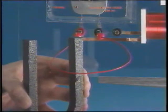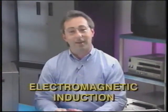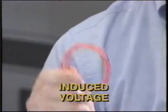So it doesn't matter whether the magnetic field is passed over the stationary wire or the conductor is moved through a stationary magnetic field. Both actions will induce a current to flow through the wire. This process is called electromagnetic induction and is the principle behind the generation of AC electricity. In order for it to occur, either the conductor must move or the magnetic field must move. The voltage generated in the conductor is called an induced voltage.